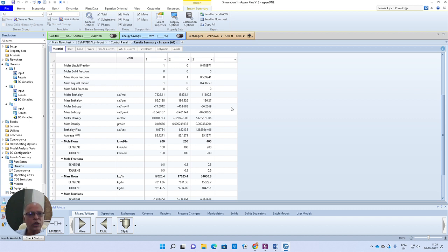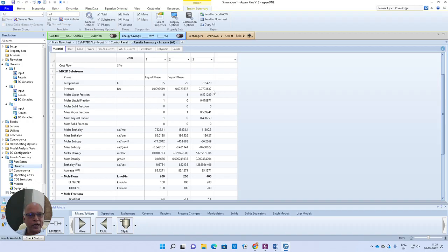So we know the pressure of the exit stream, the composition of the exit stream, we know the enthalpy. Now, how do you think you will be able to calculate the temperature? Please think about this question, whether you are in a position to calculate this temperature or not. In fact, in the simulator, it will be performing an adiabatic flash. That's how this temperature is estimated. You can probably verify this calculation if you are able to do by manual calculations.